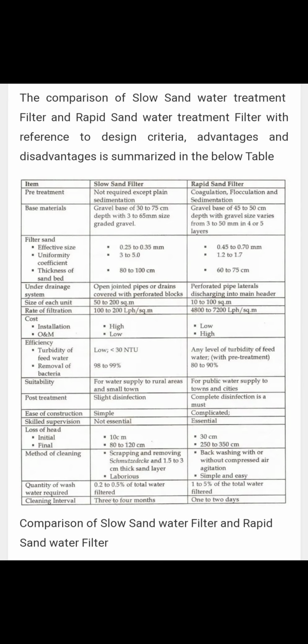And if you are considering the rapid sand filter, it requires coagulation, flocculation and sedimentation. So these various processes are the pre-treatment required before use of a rapid sand filter. That means it is important to remove all suspended and colloidal impurities before entering the rapid sand filter.